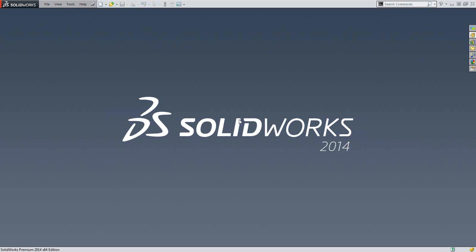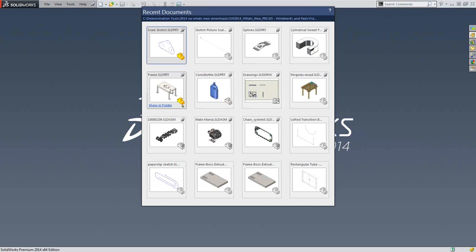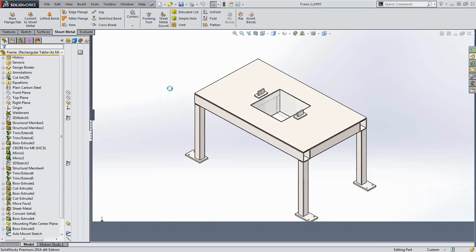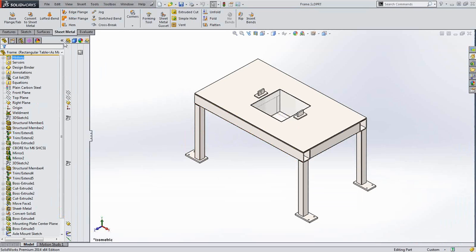Now let's take a look at the weldment features as well as just multi-body parts in general. So weldment tools, mainly the structural member tool, is commonly used for steel framework like this. The name can be misleading. It doesn't necessarily have to be weldable materials. It's just things created with common standard profiles.